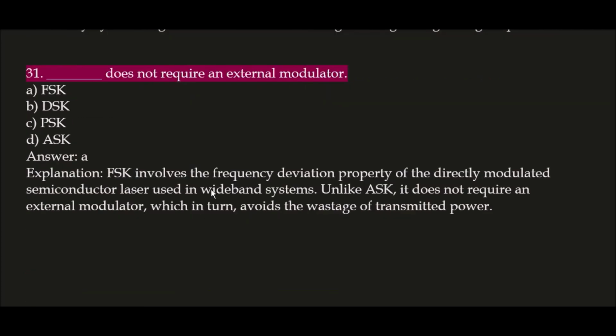Okay. Next question. Blank doesn't require an external modulator. Correct answer is option A, FSK. FSK doesn't require an external modulator because FSK involves the frequency deviation property of the directly modulated semiconductor laser used in wideband systems. Unlike ASK, it doesn't require an external modulator, which in turn avoids the wastage of transmitted power.